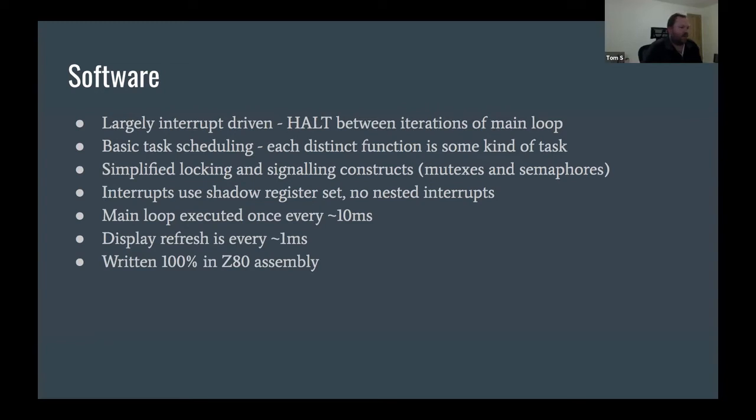This might make a little bit more sense when I get into more of the details of how the software is actually put together. I've got a bit of a concept of tasks and task scheduling to do a lot of the work in the clock software. Each task does a distinct thing. So, I have a task that runs which reads all the button states. I have another task which pokes the watchdog. There is a task which implements some fancy little effect on the display when it's